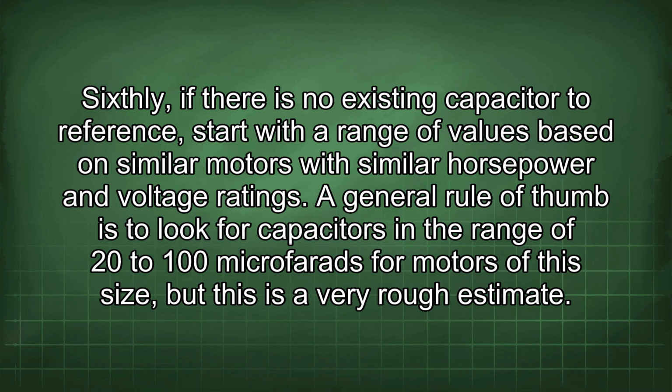Sixthly, if there is no existing capacitor to reference, start with a range of values based on similar motors with similar horsepower and voltage ratings. A general rule of thumb is to look for capacitors in the range of 20 to 100 microfarads for motors of this size, but this is a very rough estimate.